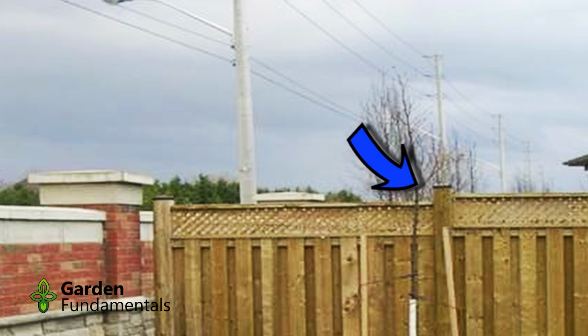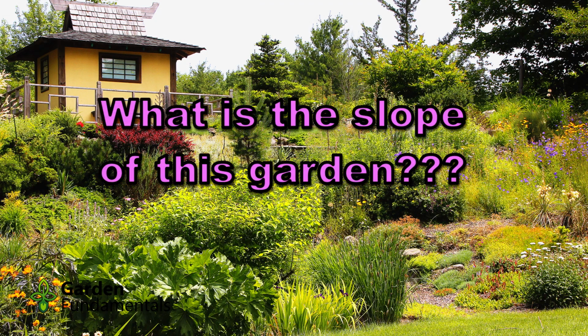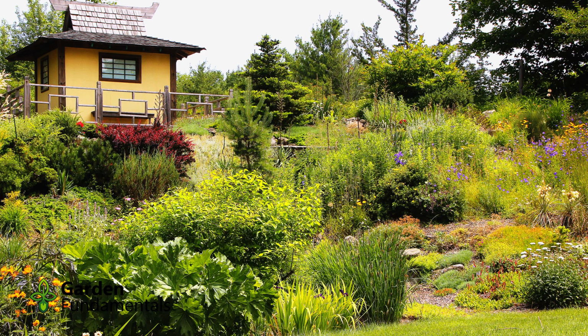So if I have a fence going in the right direction, I can get slope that way. But the previous way I showed you to get slope, that works anywhere in your property in whatever direction you want. It is important to measure the slope. Humans are extremely bad at looking at a piece of property and seeing the slope. Our minds are designed to make everything horizontal, and so our minds correct the slope that's there. So don't trust yourself.